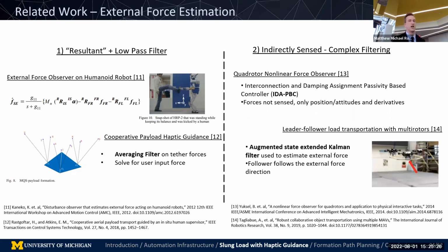In 13, they used an IDA-PBC approach, where they had positions, attitudes, and derivatives, and then had a model of their system such that they could compute what the forces sensed were. Additionally, in 14, focused on the load transport problem, they used an augmented state extended Kalman filter to estimate that external force. And if you notice, there are follower vehicles and leader vehicles. What they did is the followers were estimating those forces and following along, and somebody was commanding those leaders.